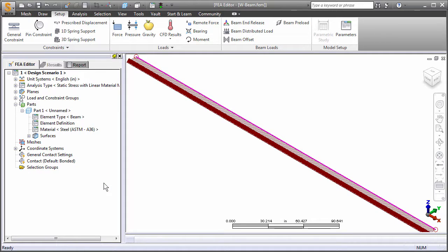Note that beam elements must be oriented correctly, since the line that represents the cross-section cannot dictate on its own whether the beam is horizontally, vertically, or otherwise oriented. The default surface number for a line is surface 1, and we did not change the surface number when we drew the beam. In Simulation Mechanical, lines on surface 1 orient the beam such that the depth of the section, local axis 2, is in the global y direction.